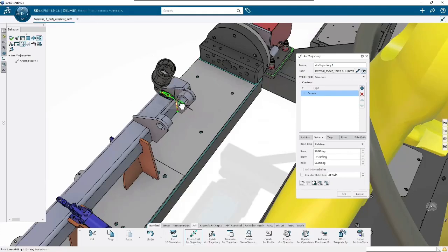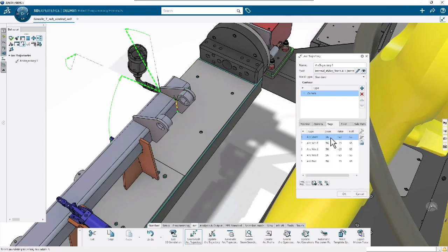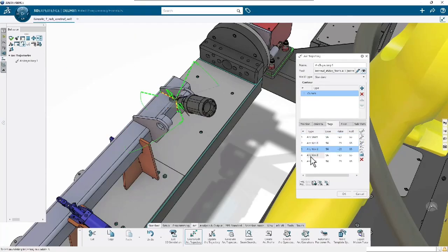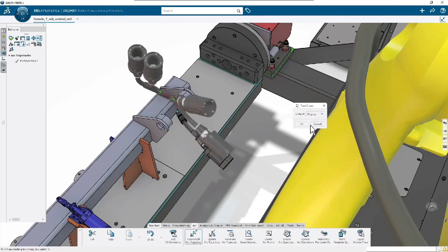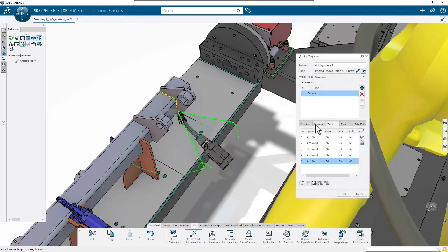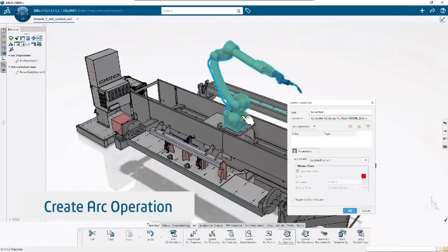And you can see and modify your tooling trajectory and make sure that it lines up with each of the tags. You have the reach in that view. You can also create a tool cloud, which automatically puts that tool at each of those points for visualization. Helps a lot of times if you're having issues and need to explain what's wrong.